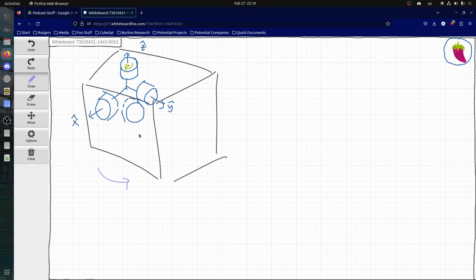And by tuning that and controlling it using a feedback loop, you can control the attitude of the spacecraft. Yeah, so on the screen, this is the redundant wheel. So you have one in the X, Y, and Z, and then you have one that's pointing in all three. Normally, if you're using four, this is not the optimal configuration, but it is a configuration.